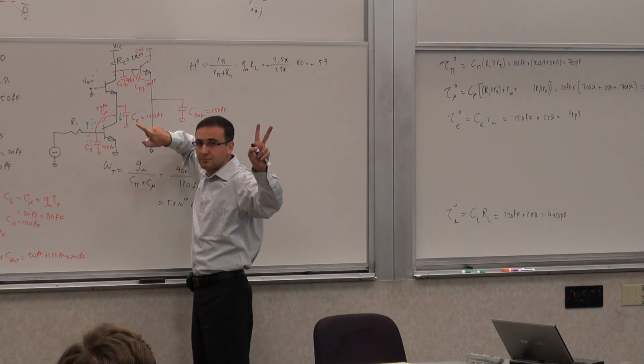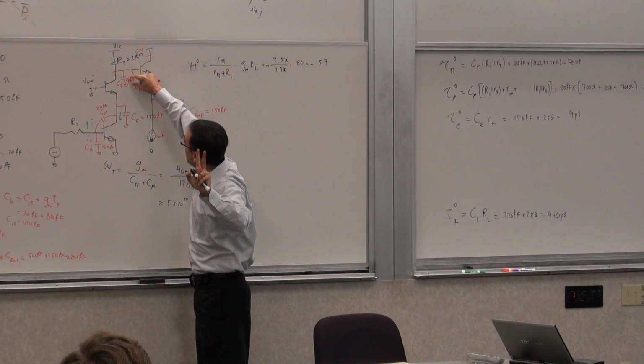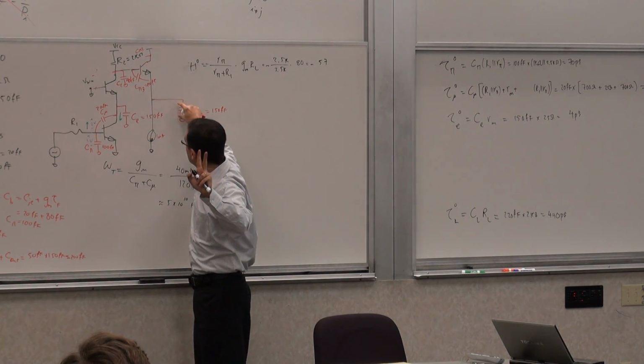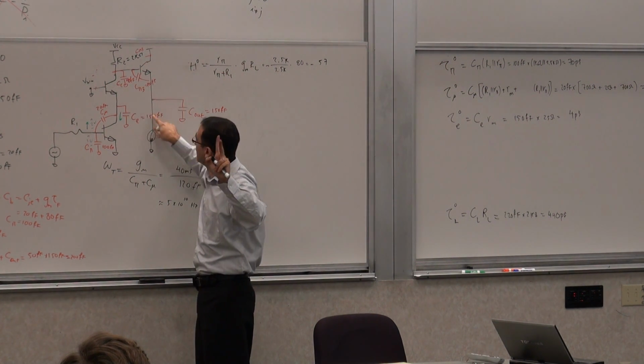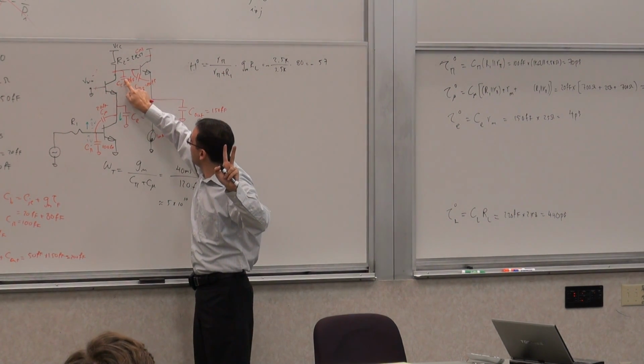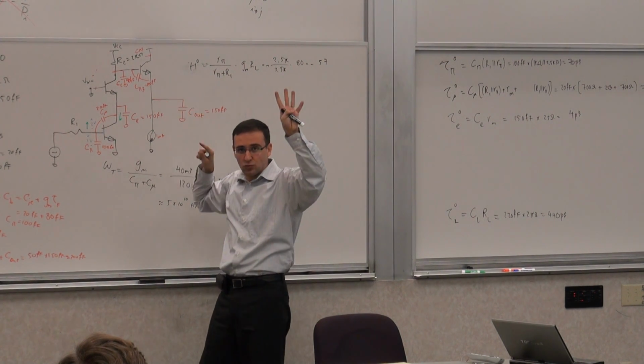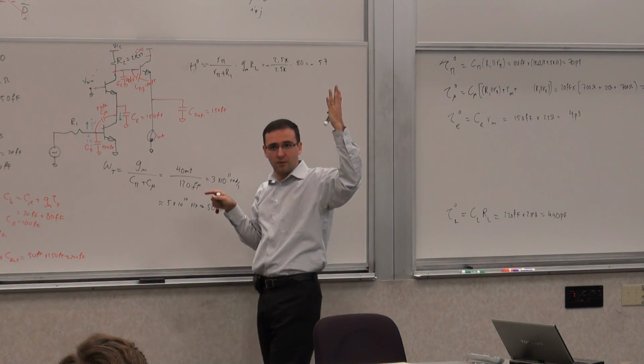Yeah, and also the same situation for those 3 capacitors. Because if I determine this voltage and that voltage, then this one is determined because these are forming a loop through the ground. So if I make this 1 volt, make this 2 volts, this is 3 volts already. So then I get 2 more. So how many poles? 4 poles.